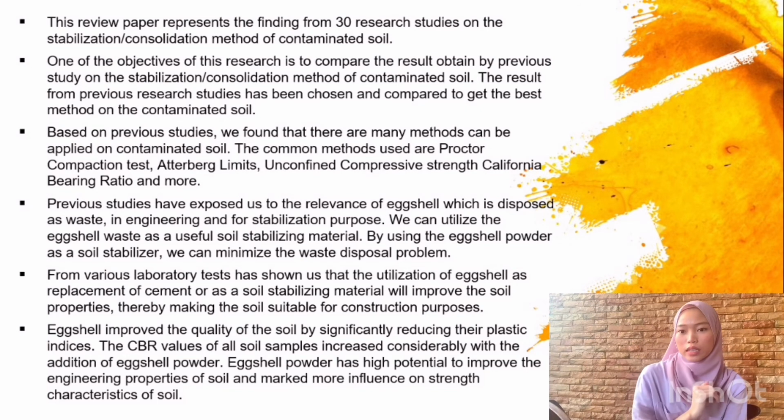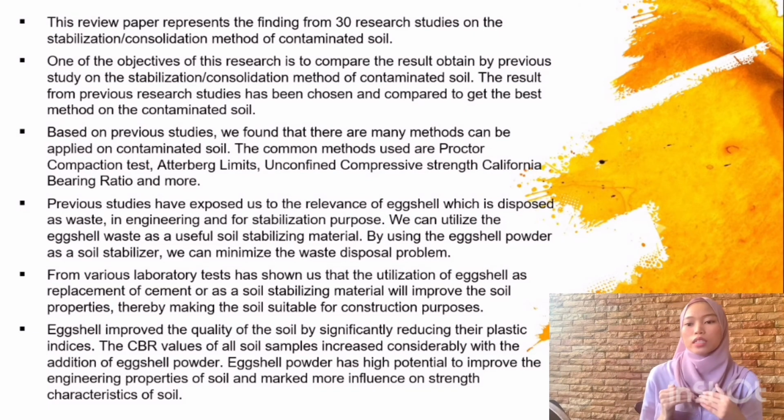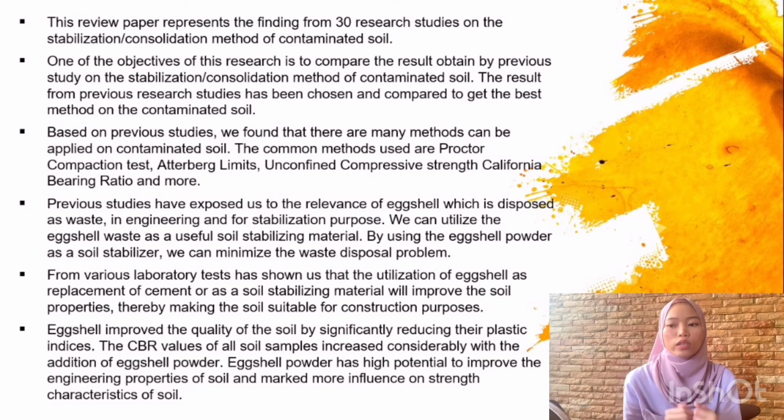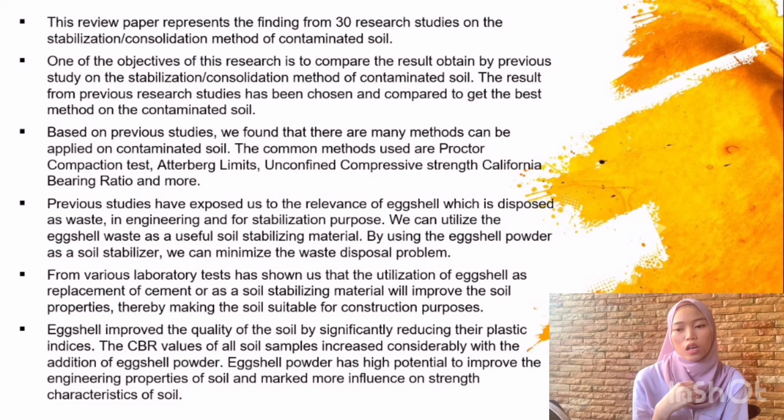Based on the previous studies, we found that there are many methods that can be applied on contaminated soil. The common methods used are the proctor compaction test, Atterberg limits, unconfined compressive strength, California bearing ratio, and more. Previous studies have exposed us to the relevance of eggshell waste, which is disposed of as waste, in engineering and for stabilization purposes. We can utilize the eggshell waste as a useful soil stabilizing material. By using the eggshell powder as a soil stabilizer, we can minimize the waste disposal problem.